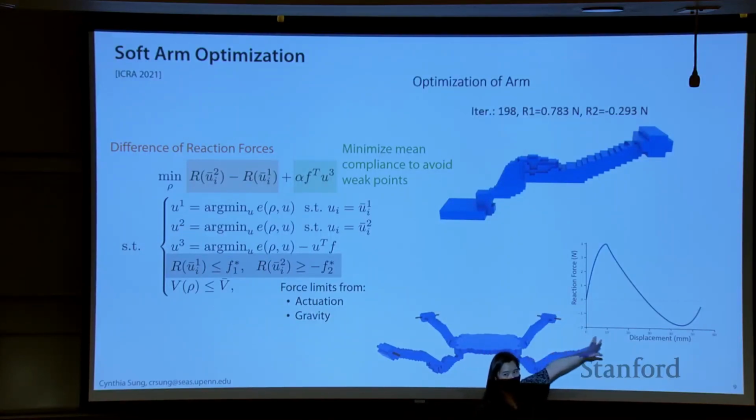And so the idea here is that through this optimization, we were now able to achieve this bistable mechanism where each of these beams is attached to the frame of the quadrotor, and we have a big mass in the middle, right? So changing the location of this mass results in reaction forces from these beams that look like this curve. And if the vehicle accelerates and this platform is pushed past a certain point, this 0 right here, then the vehicle will automatically switch modes, right?